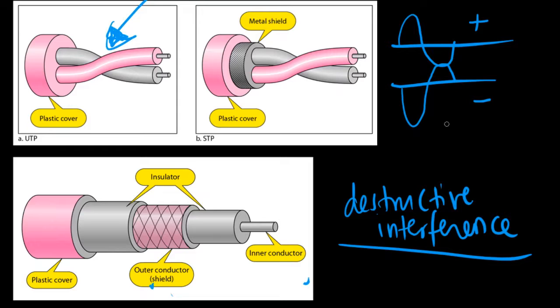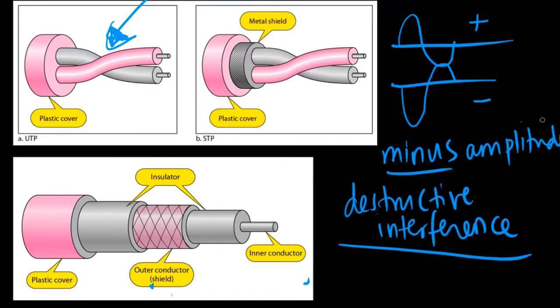And as you may know, the amplitudes of our signal get subtracted, and if they are about the same amplitudes, then the signal is lost. At the end of the line, you will receive a flat signal. Almost nothing. So, what they did is to twist it, and with that, their sine waves are not aligned. And therefore, the interference between them is reduced. The destructive interference is reduced.